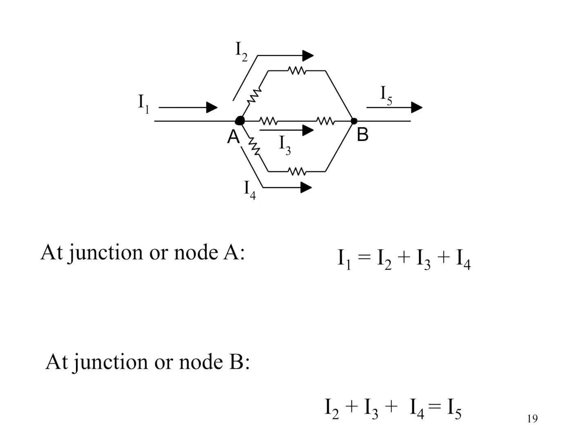So it's no longer a point. A point is a point of reference in a circuit for voltage, where there's one input, one output, and a node can also be a point as well. But here, this is definitely a current division node, because we've got current entering and then current being divided into three exiting paths. Notice how the current entering is described as I1, which we know has to equal the sum of the current exiting: I2 plus I3 plus I4.